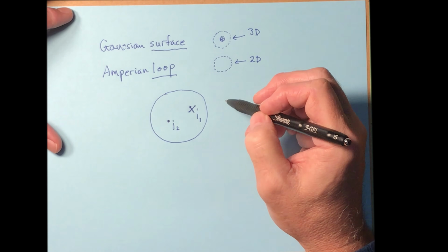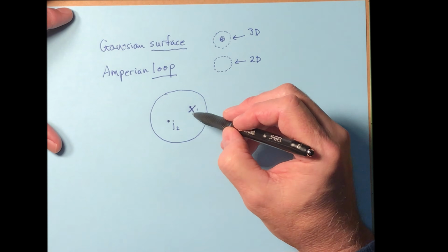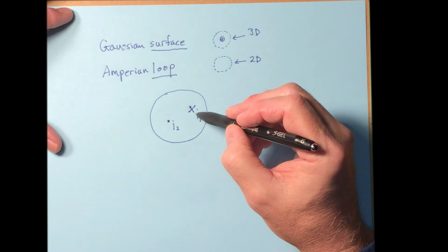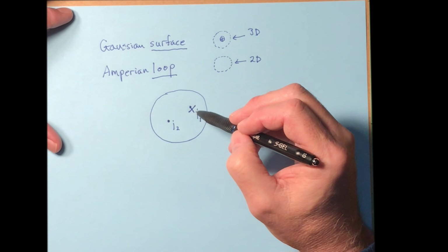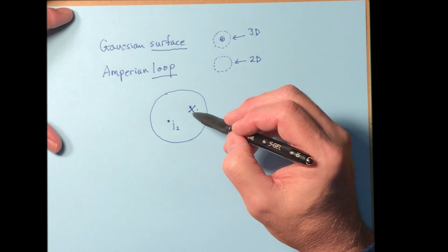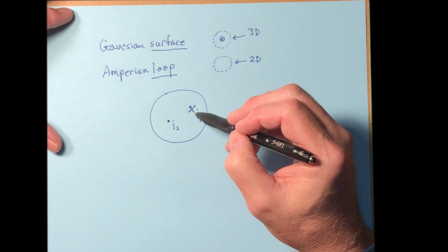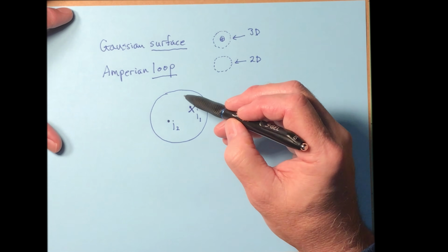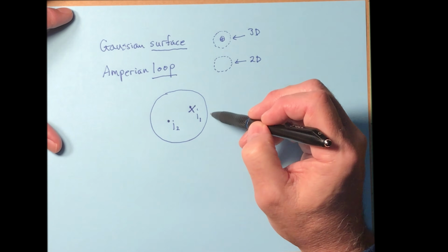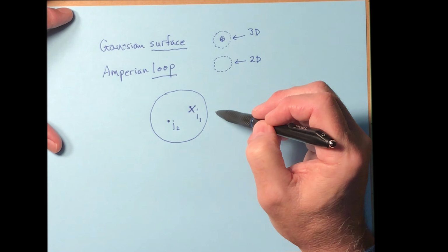All right. Which one of those is the positive current and which one is the negative current? To be honest, it can be either one, but whether or not you call something positive or negative doesn't depend upon you just choosing it. It depends upon the direction in which you traverse this loop here.